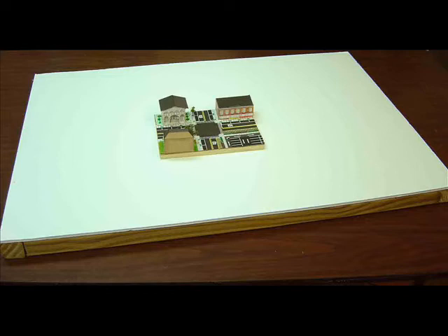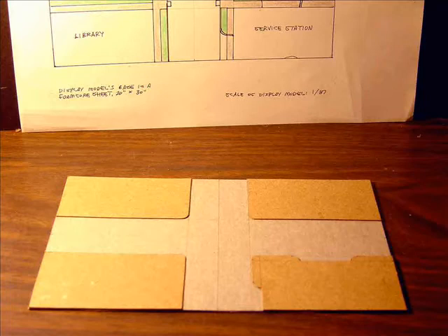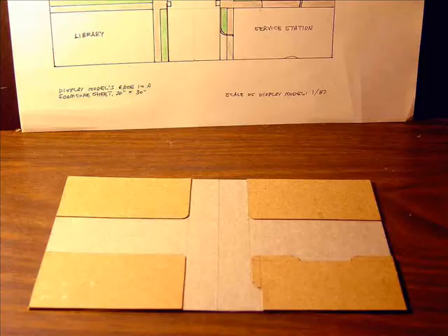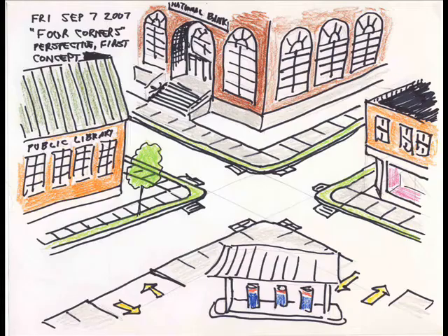We now begin constructing the superstructure of the planning model. By superstructure, we mean those parts of the model that stand upon the baseboard. In the case of Four Corners, which represents 4 building sites at the intersection of 2 streets, we add the building sites as shown in the designer scale diagram. The 4 building sites encompass the outlines of the future sidewalks, curbstones, and construction areas.